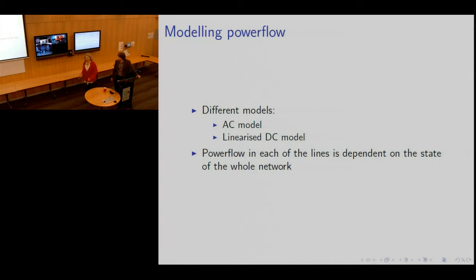We also have an approach that's using MIP or NLP or quadratic programming with some relaxation of power flows, and that's working better than this. Also, this is solving a potentially much harder problem, because you don't have to specify the number of time steps that you're using in your plan, which you would have to do with a MIP or NLP or something like this. Okay. Yeah, thanks very much.